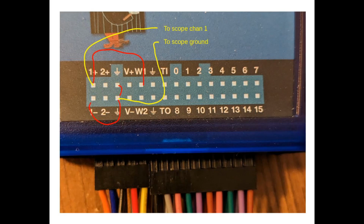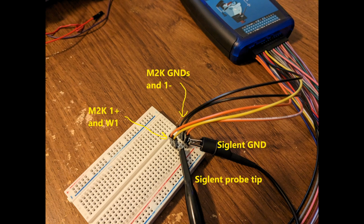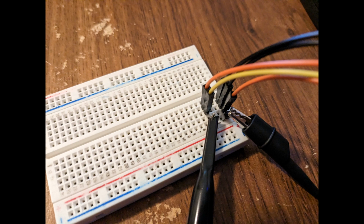This is the connection setup. We'll have the 1 plus pin of the M2K connected to the W1 signal generation pin, and then the 1 minus pin connected to ground. At the same time, we'll have the scope ground connected to the ground and the Siglent scope channel 1 connected to 1 plus. The connections are made using a breadboard, as you can see here. And of course, flying leads and a breadboard, this is not the best probing solution. So we might expect to see some artifacts at high frequencies.